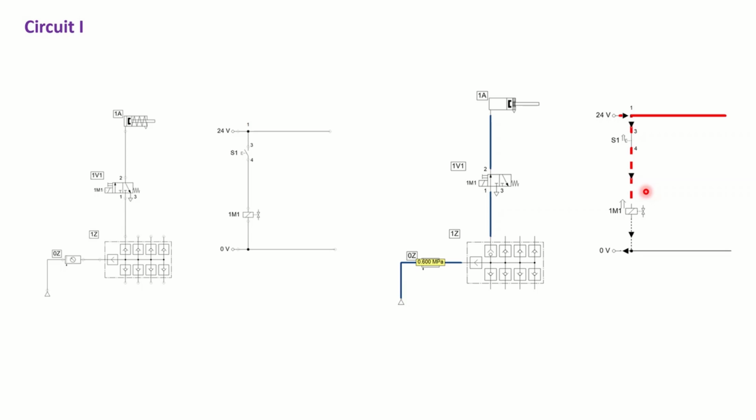As you can see, there are two new components inside the electric circuit that we didn't discuss in pneumatics, and those are the solenoid and the push button switch. Also I can mention the power supply, 24 and 0 volt, which provides the difference of potential, and from there we would have the current. That is a new part. So it is a very simple circuit which provides the same functionality as the circuit that I designed in our first video.